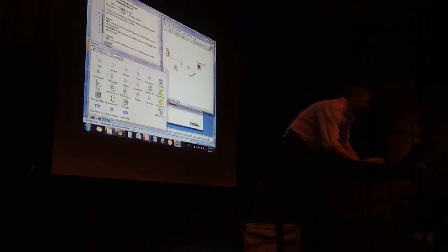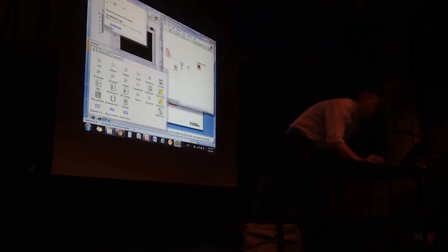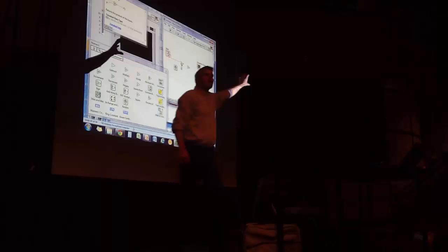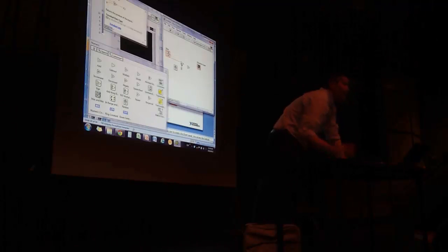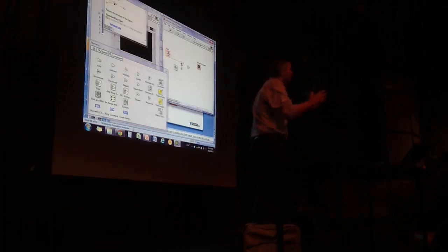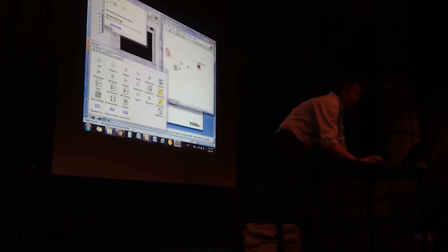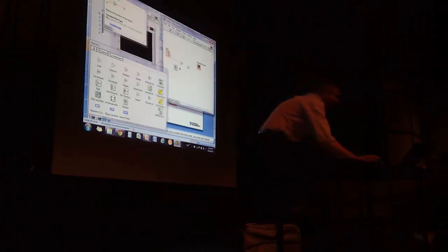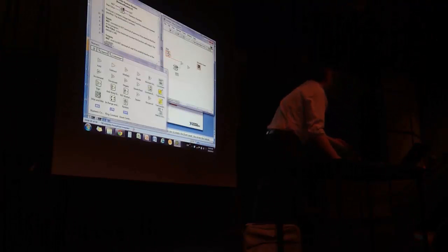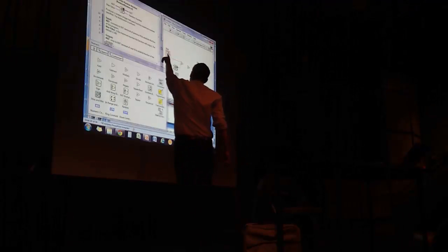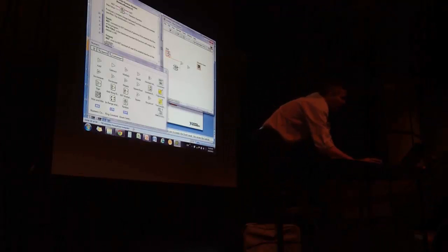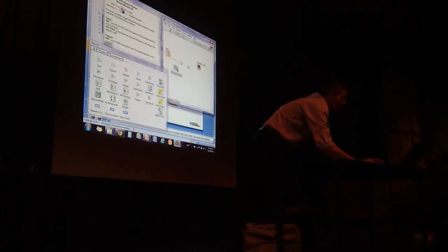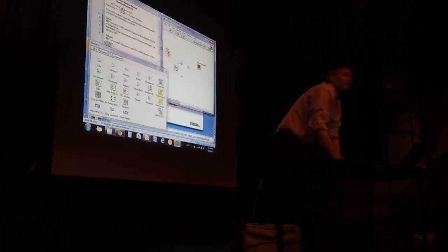So, let me explain how you wire. If I go to one of the terminals, I see that it's blinking. So that's how I can start wiring. If I make a left mouse click, it's kind of like soldering the wire to this function. I can see that I'm now dragging a wire, and then I can drag it to the next one. And if I have the help menu open, I see now I will connect it to the NXT input, which is the wrong output, sorry. And if I connect it down here to the random number, I can just connect it directly to this.